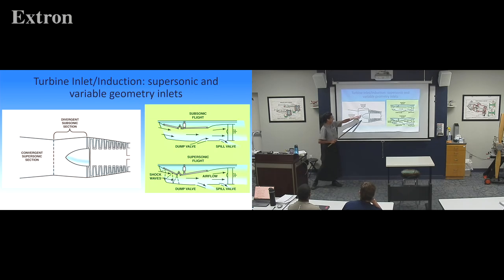Said, now we can widen that out to increase pressure. But they design these, and these are super smart engineers. They know how to shape this. They've done lots of tests so the shock wave happens at the right place. Poof. Now we have subsonic air. And this concept is that you can change the geometry so it can be doing whatever you need, whether you're starting off subsonic and then transition through to supersonic.